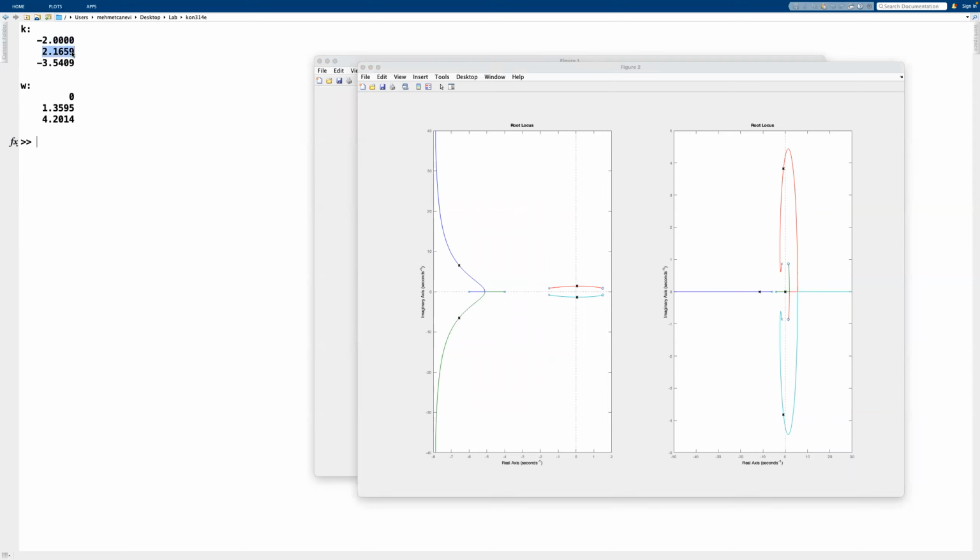But now it's 2.16. Now, this Padé approximation tells me that between 2.16 and 2.43, the actual system is still unstable. That's why I'm telling you that this interval tells me where the system is not stable, instead of telling me if it's stable in that interval. So outside of 2.16, now I have narrowed it down a little bit more.